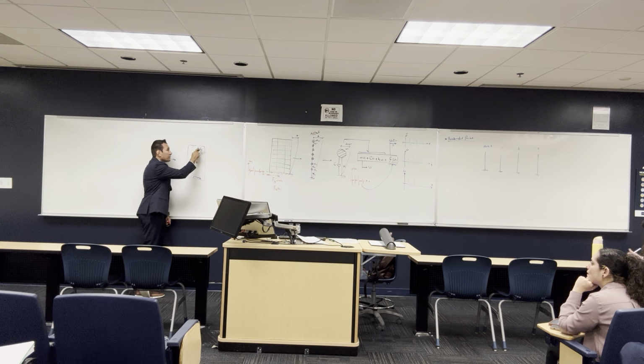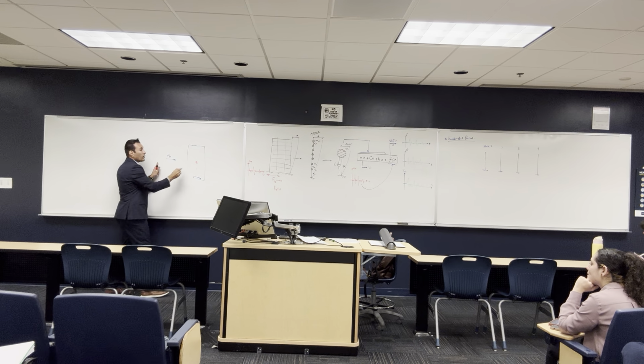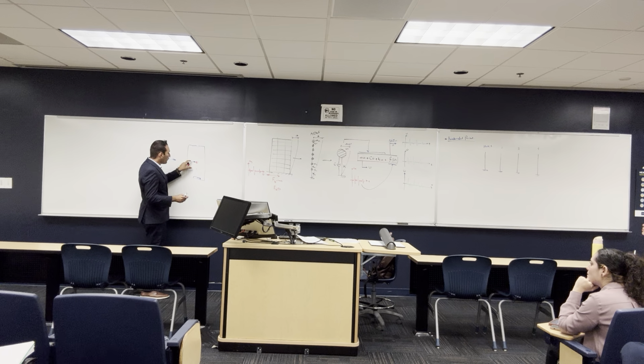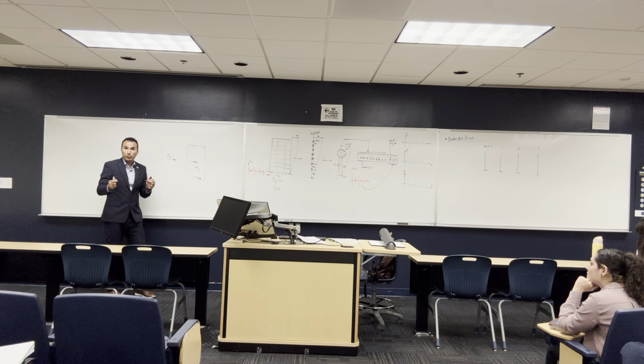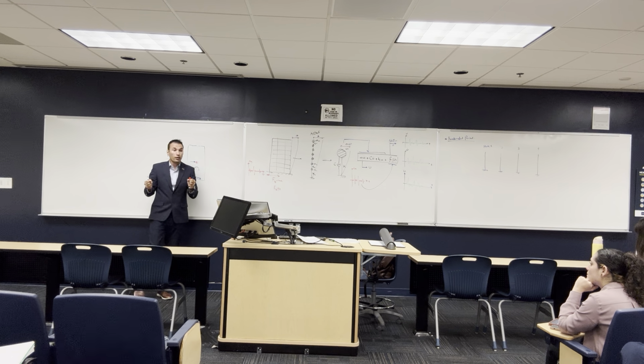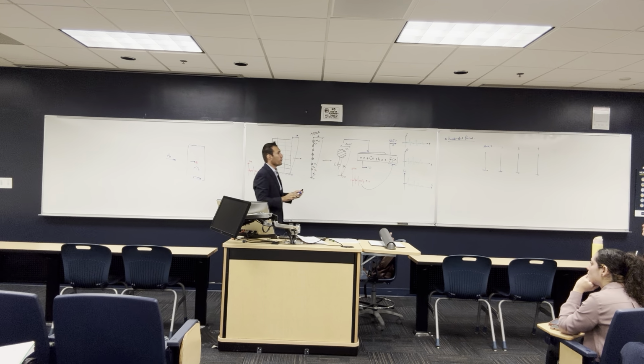But since this is not here, and we only have one, the center of rigidity is gonna move a little bit down toward this, so it might be here. But when the force of the earthquake hits, it always hits at the center of mass of the building. So when you multiply this force with this distance, it's gonna give you a moment around the center of rigidity of the building. So it's gonna make the torsional movement. This is just for your record.